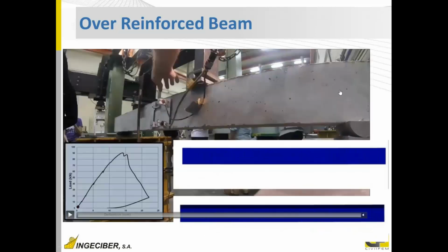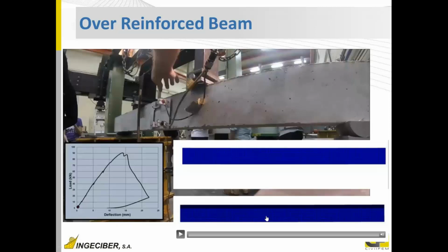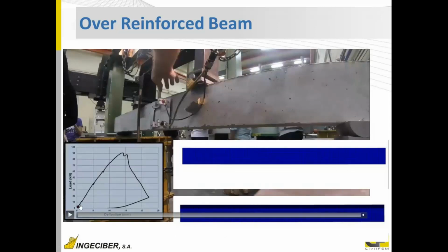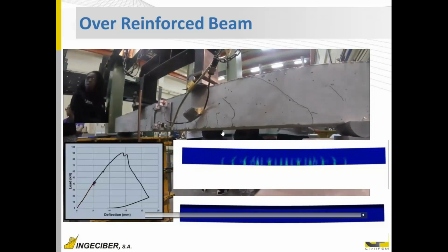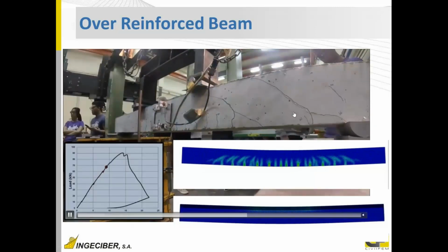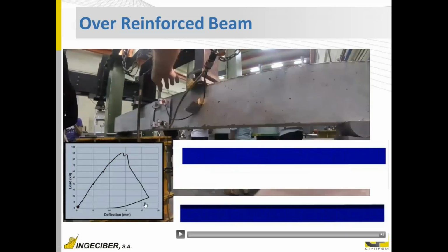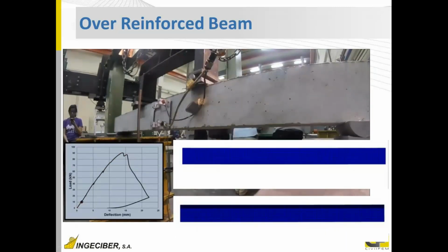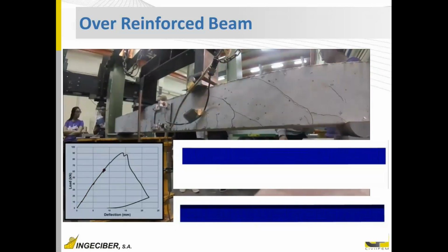If we compare the crack patterns, there are not high cracks for bending, I mean not penetrating a lot, short, similar. The shear cracks are longer, but not very wide, and the crushing zones, which is the most important, and which is the failure of this model. So in this video, we are going to compare the real test. Here we will plot cracking, and here we will plot compression, deformation, and crushing. And here we will see the relationship between load and vertical displacement. We can see first cracking has started appearing here and here, similar. Shear cracking has started appearing, and then here just crushing. Crushing happens. Let's see the video. First, again, cracking at the bottom of the test and also in the CivilFEM model.